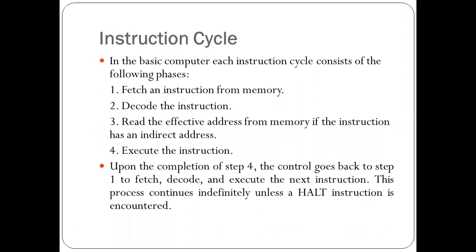These are the steps that have to be done for a memory reference instruction. For a register reference instruction, fetch is common, decode is common, reading memory will not happen because the accumulator itself holds the operand, but the execution will happen. If you come to IO reference, fetch is the same, decode is the same.